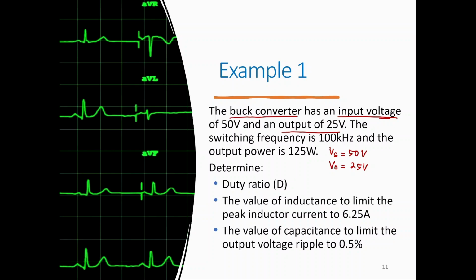If you see step up, which is your V out is greater than your Vs, this is boost converter. If it can be either step up or step down, it is buck boost converter.